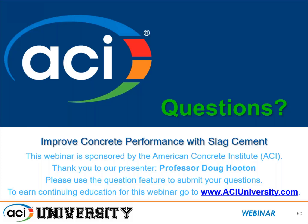All right, Doug, we do have one last question for this afternoon. Why would you want to use slag cement over a fly ash as a supplementary cementitious material in placing exterior concrete pavement exposed to freezing and thawing and thermal expansion environments? Well, a lot of what you use, whether it's fly ash or slag, depends on what's available in the marketplace. And also, as I mentioned, slag doesn't have a negative impact on the air entraining dosage required to get a consistent air content and get the right bubble size distribution for frost resistance.